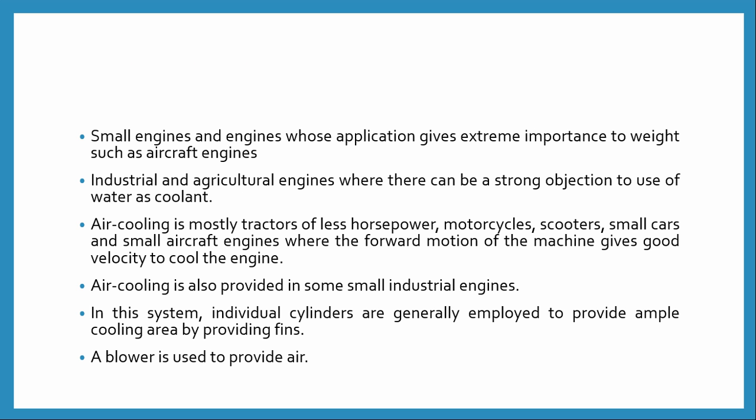So in very small engines, and engines whose application gives extreme importance to weight, such as aircraft engines, and industrial and agricultural engines, where there can be a strong objection to using water as a coolant, air cooling is used. It is mostly used in tractors of less horsepower, motorcycles, scooters, small cars, and small aircraft engines, where the forward motion of the machine gives good velocity to cool the engine.